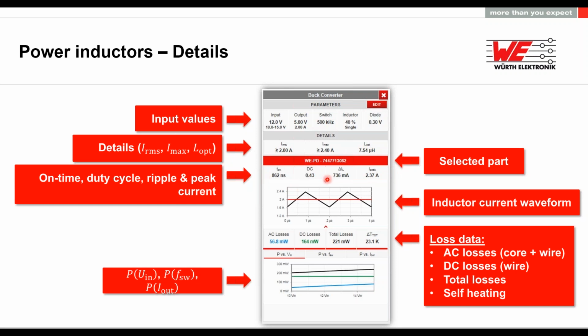The tool calculates and shows you the T-on time of this topology and the duty cycle, the inductance, the inductor's current, the inductor's ripple current, and the peak current. Also here you can see the waveform, the current waveform of the particular inductor which you have selected.